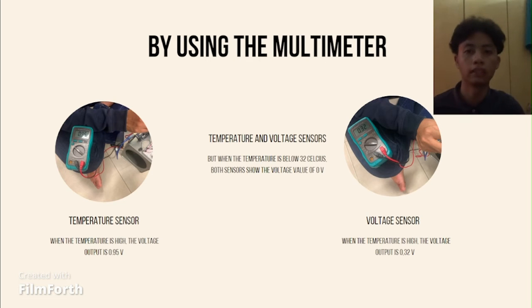So the next one is by using the multimeter. So as you can see at the left side, this is a temperature sensor. The temperature sensor has a 3-pin output, which is the sensing in the middle. At the right side is the ground, and the left side is the positive. So we connect the positive terminal from the multimeter to the sensing feed at the sensor. The black terminal, which is ground from the multimeter, we connect to the ground. So when the temperature is high, the voltage output is 0.95 volt.